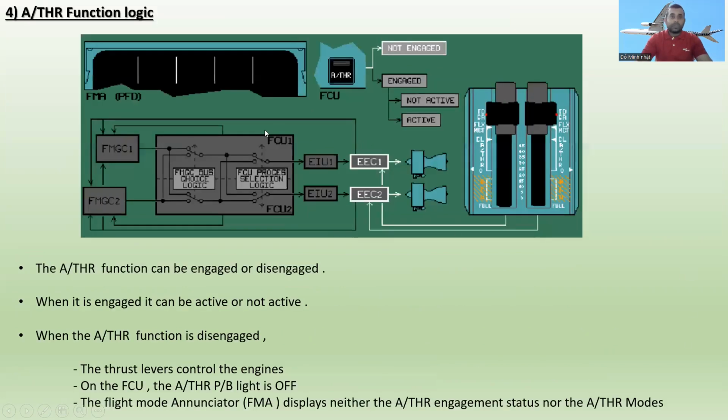Now, autothrust function logic. The autothrust function can be engaged or disengaged, and when it is engaged, it can be active or not active. When the autothrust function is disengaged, the thrust levers control the engine.